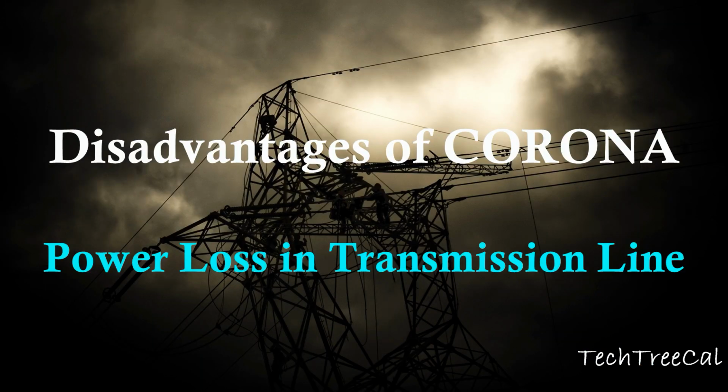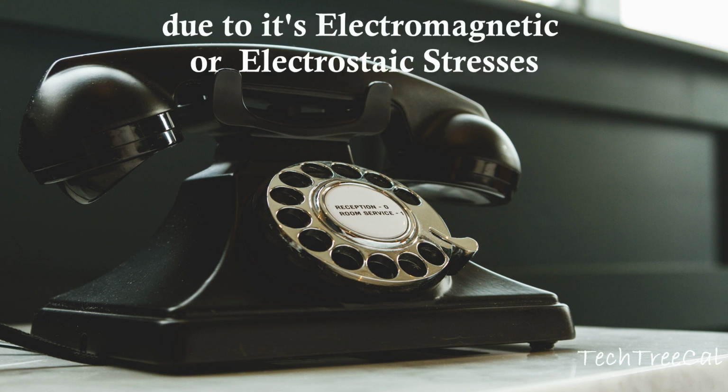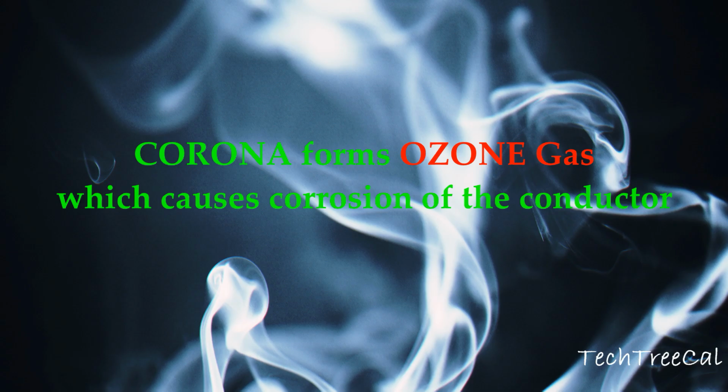Corona effect causes a certain amount of power loss, though this only happens in abnormal weather conditions, as the corona effect is not visible or does not occur in normal conditions. Corona causes interference with the neighboring communication system due to its electromagnetic or electrostatic stresses. As corona produces ozone gas, there is corrosion of the conductor due to the corona effect.